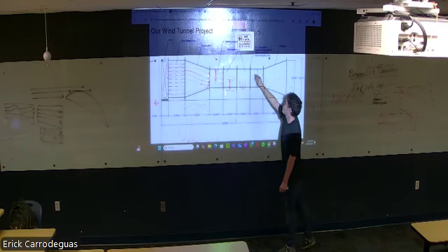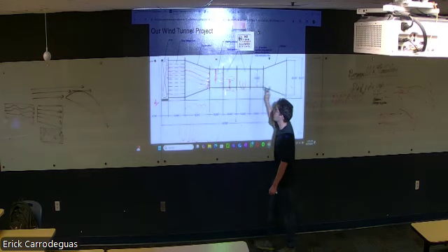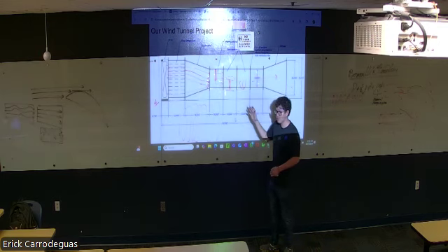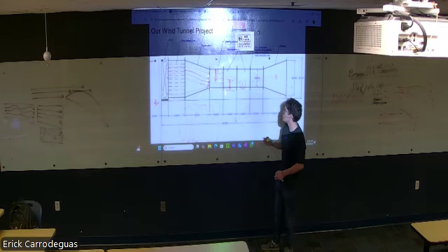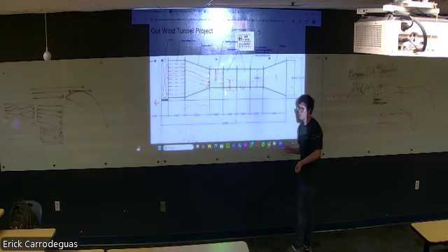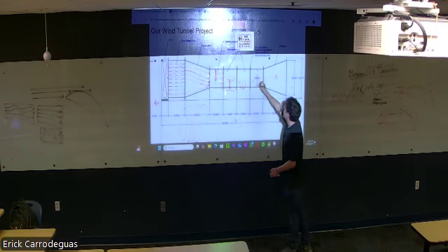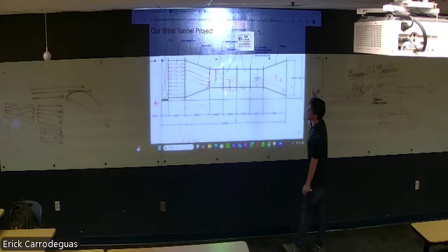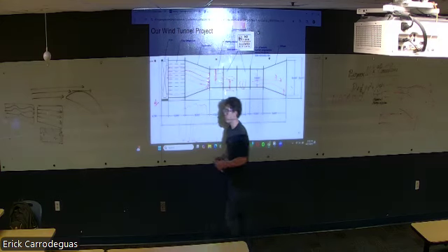So as air travels back out, in order to keep it laminar here in the test sections, we need to reopen. And as this reopens, it's no longer laminar, it's more transient airflow. So Reynolds numbers of 2,300 all the way to 4,000. And it just goes back out from speeds of 30 miles an hour back to 15 miles an hour, just like a regular fan. And then it just goes back out to the environment. It's open circuit.